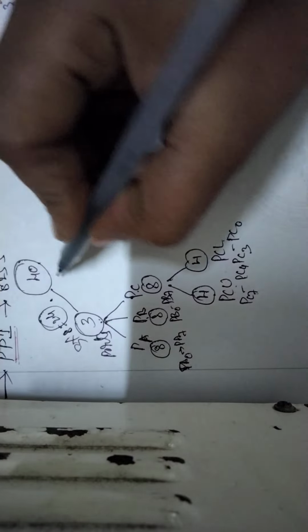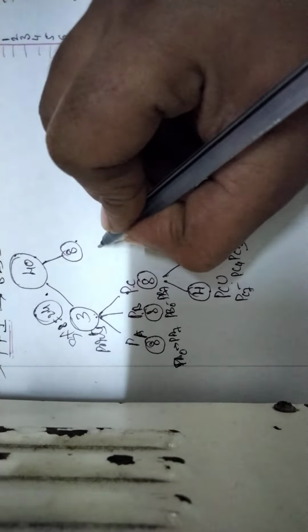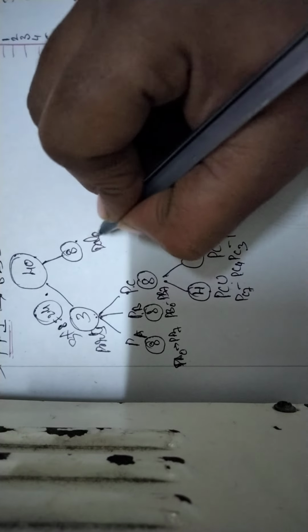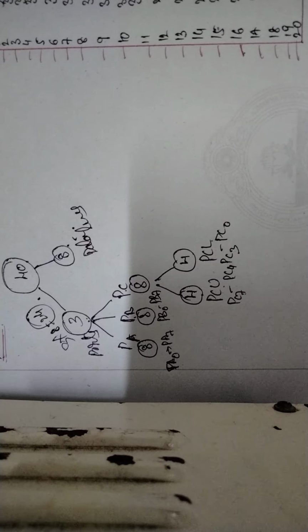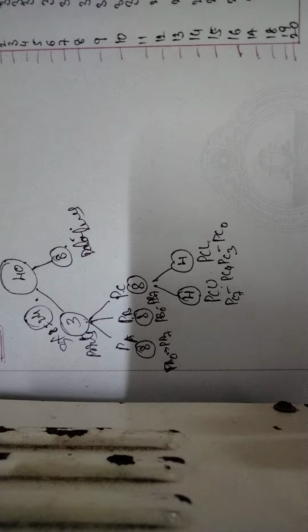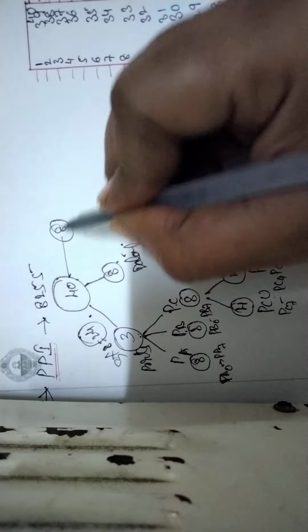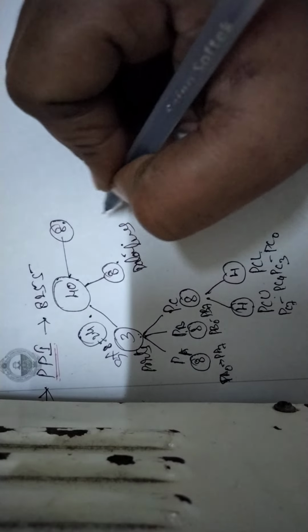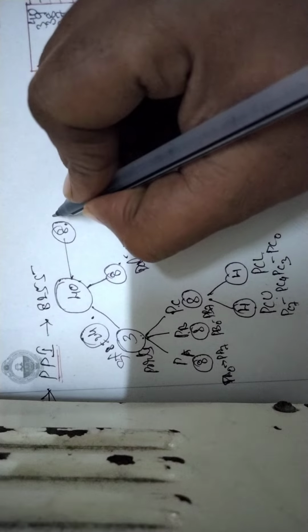So next, 8 bits are for the data buffer, the data lines. These data lines are used to transmit data from the controller to the peripherals and from the peripherals to the controller. That's why these data lines are used. Okay, and the remaining pins are further divided; individually each has a specific task.